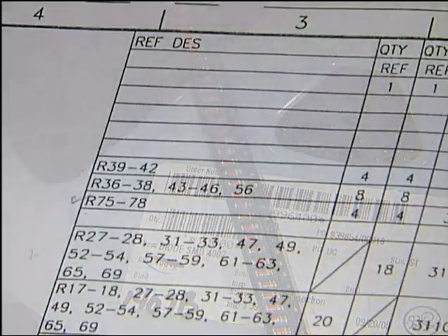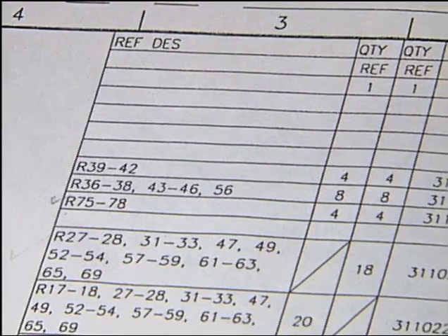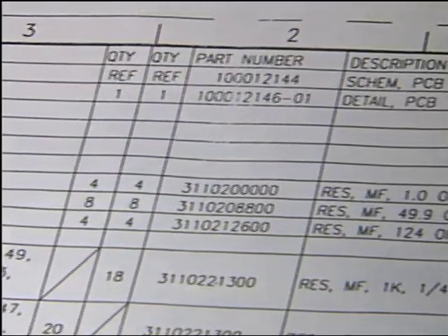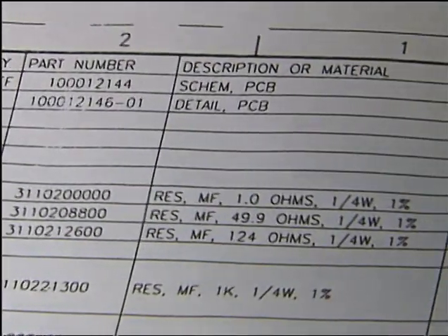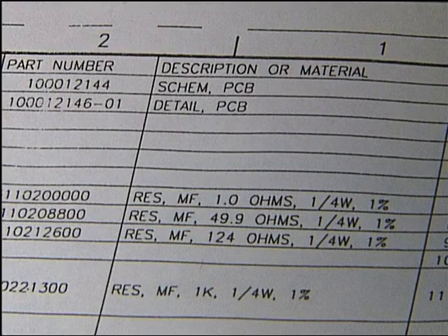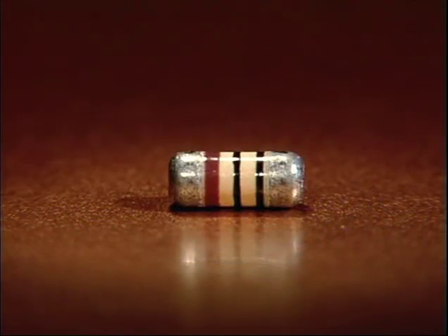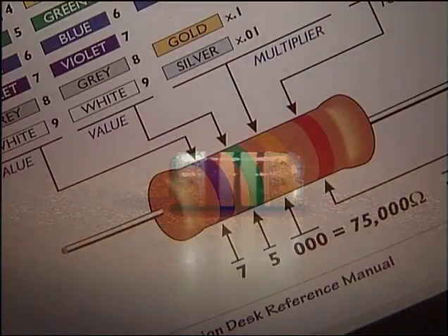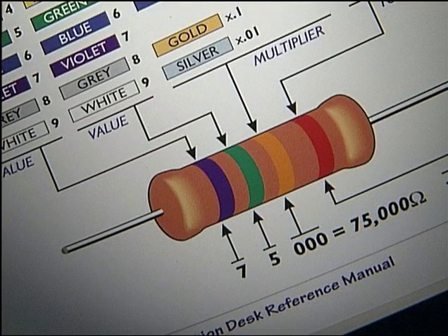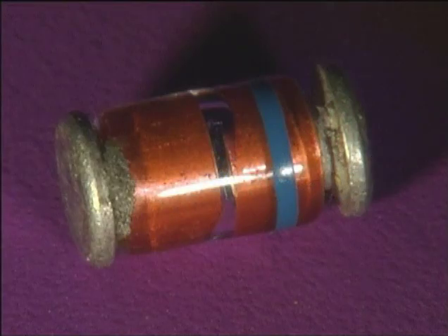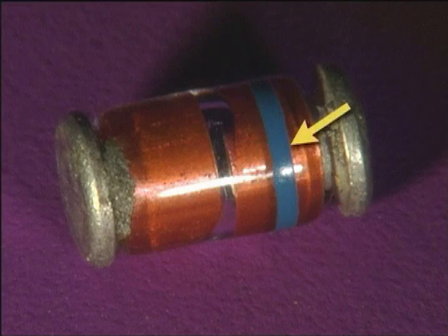Reference designators, value coding, and polarity indicators are pretty much the same for MELFs as for their surface mount chip and through-hole counterparts. For example, the color band system for specifying values and tolerances of MELF resistors, capacitors, and inductors is the same system that we used for through-hole components. Polarity is indicated on MELF diodes by a band on the negative or cathode end.